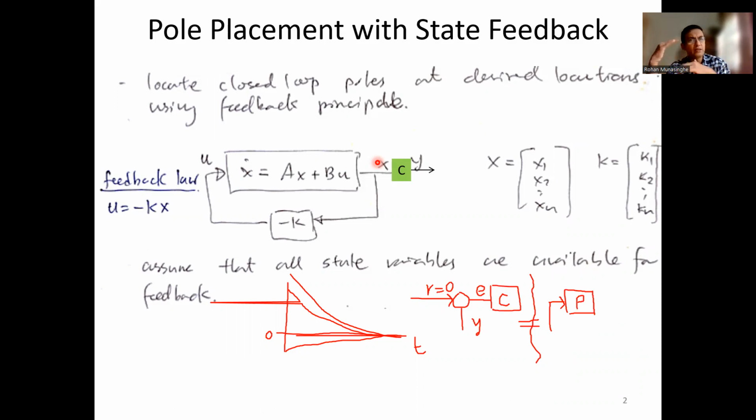If you want to maintain a certain level, you do the coordinate shifting and make sure that value is actually 0. You deduct some amount. So in control systems, when you say 0, it doesn't mean it's absolute 0. Whatever value you want to maintain is shifted as 0 by simple coordinate shifting.